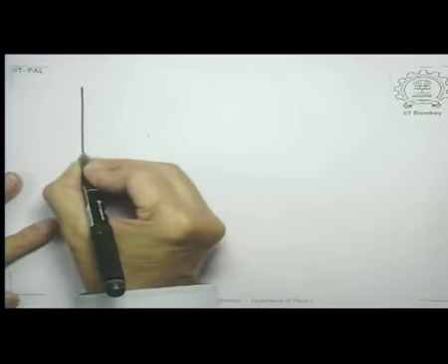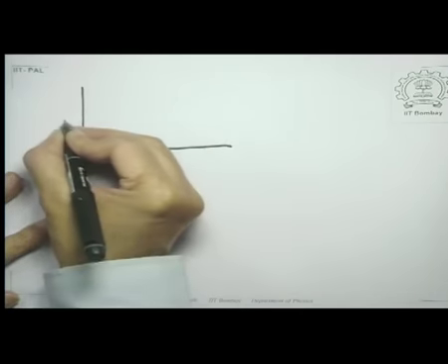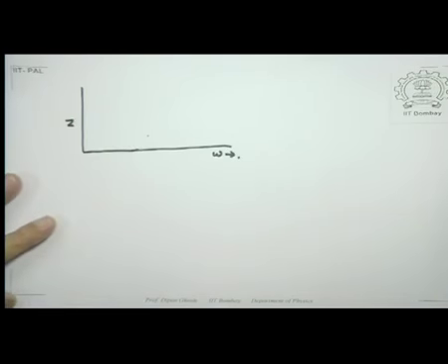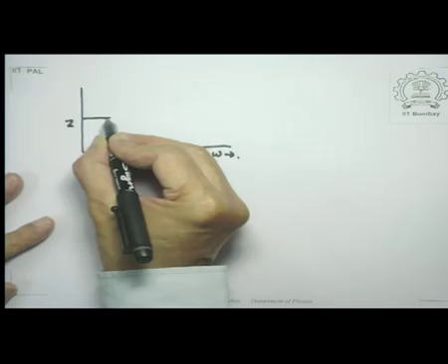It's a good idea for us to look at how impedance varies with frequency for the various types of circuit we have discussed so far. So let's try to plot Z versus omega. The simplest, of course, is the resistive circuit, and we know that the resistive impedance, which Z is equal to R, doesn't have any omega dependence. So therefore, for a resistive circuit, I simply get this.